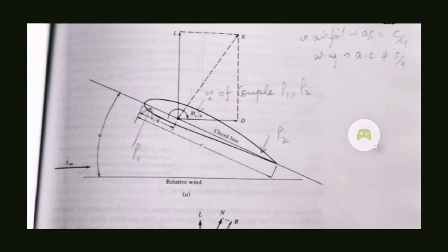So here you can see the airfoil, or you can also assume it to be a wing of the airplane. On the wing or the airfoil, the forces are represented. The aerodynamic forces you can see over here are the lift and drag, and they form a resultant R as shown by the dashed line, a vector R. And if you observe, the lift force is perpendicular to the free stream V infinity horizontal velocity, and drag force is parallel to V infinity.